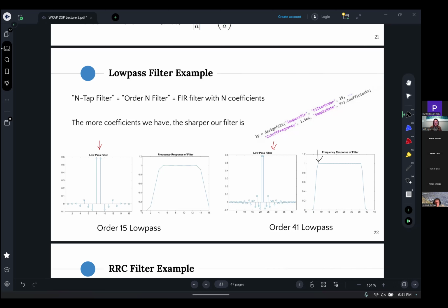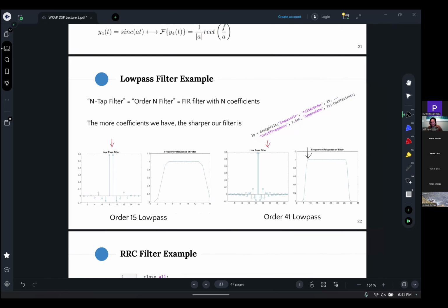So then the digital system doesn't have to worry about calculating this or doing all of these optimizations. It just has the filter ahead of time. And it also lets us switch out the filter at any time. So I could click a button and my low pass filter in software suddenly becomes a high pass filter, which is another benefit of this. Okay, thank you. Yep.